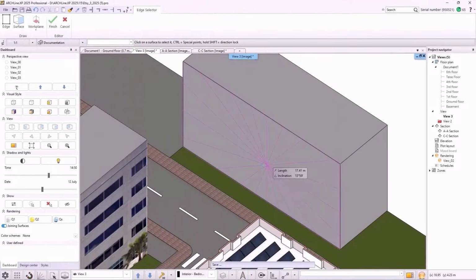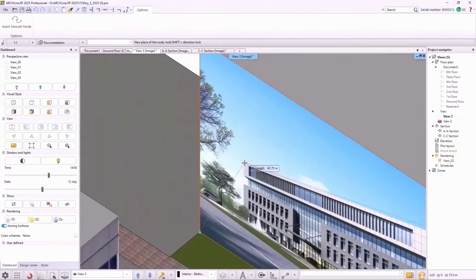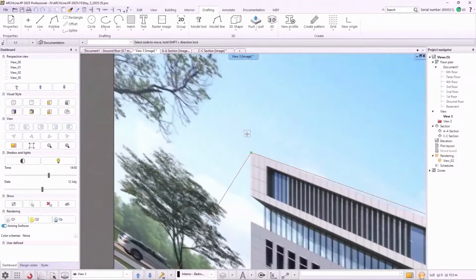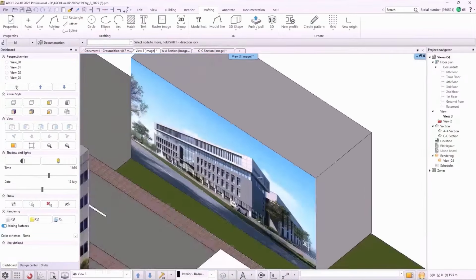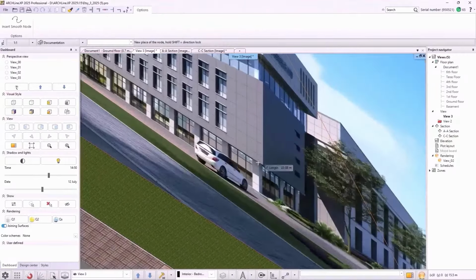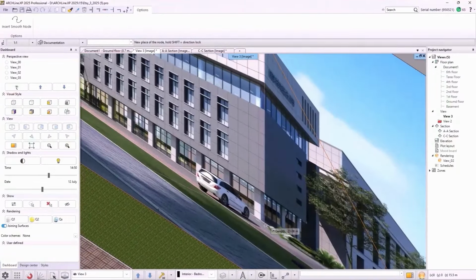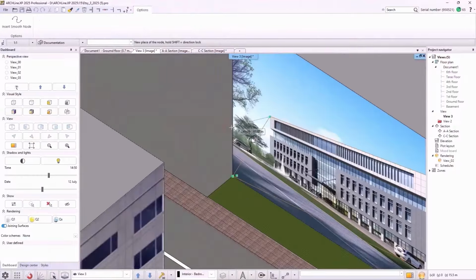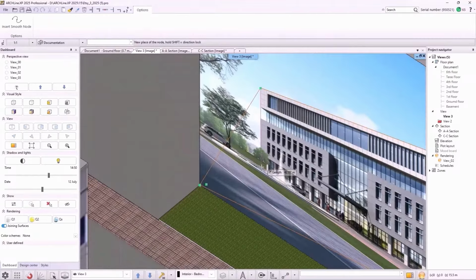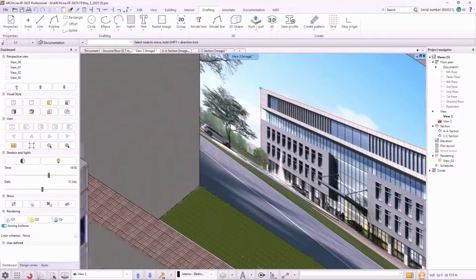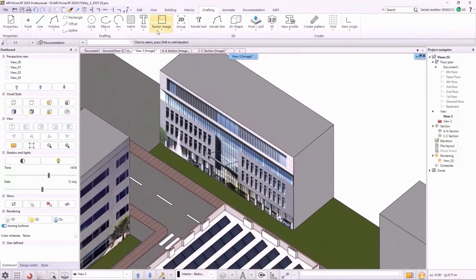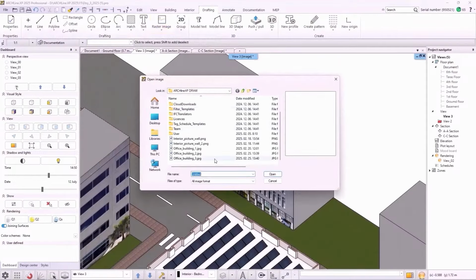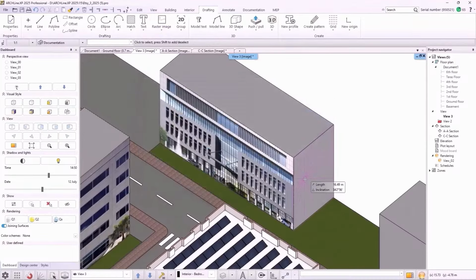Import another picture and place it on the other building mass. This time the office building in the picture has indents and extrusions from the main body. In this case, not only the corner points, but their connecting lines are helpful as well. Place the corner points that you can identify easily, and then set the other corners with the help of the edge lines. If done well, the building mass and the picture's building edges will be aligned perfectly.